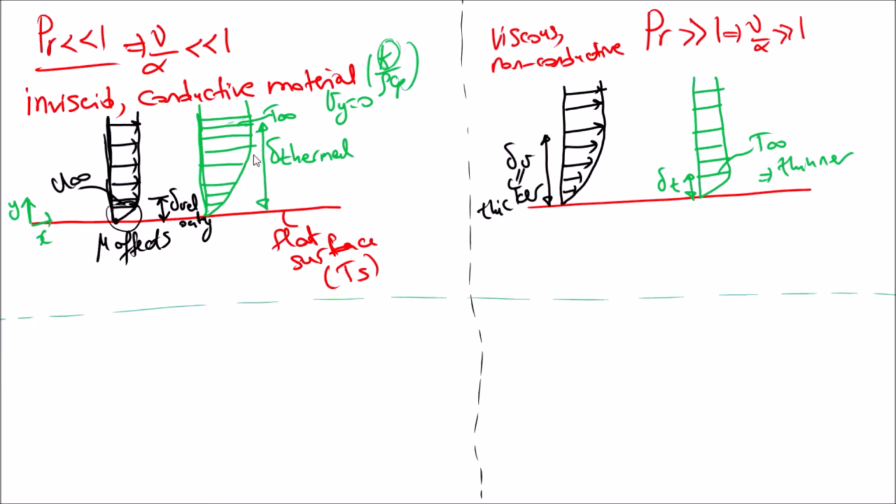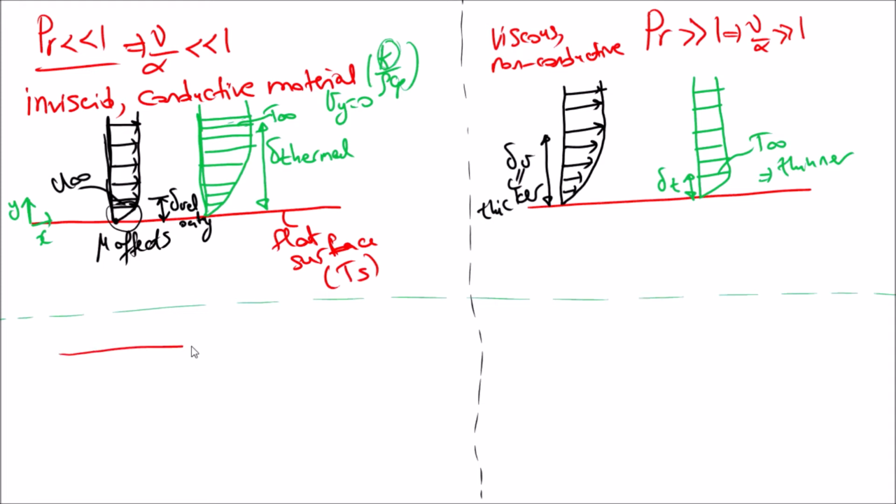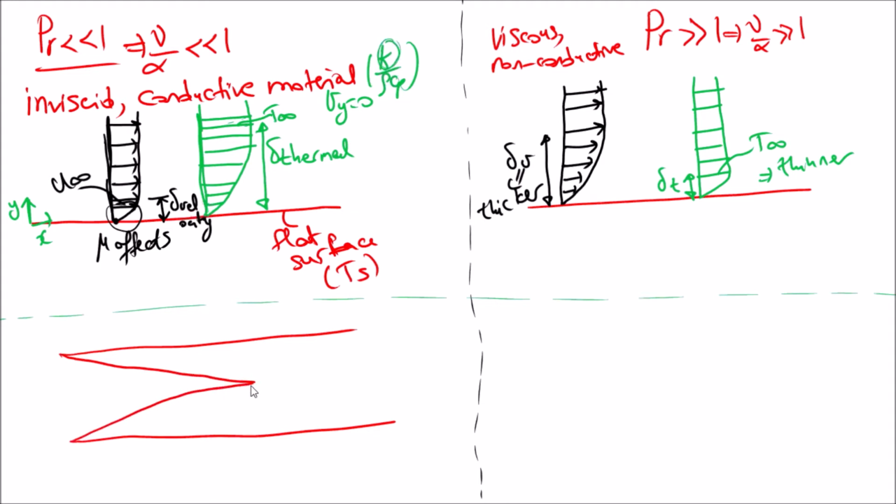Second importance of the Prandtl number is that if the Prandtl number is low, so if you go, this is your pipe. If Prandtl number is much less than 1, we have said viscosity is small. If the viscosity is small, then the boundary layer grows at a very low speed. Okay. If it grows at a very low speed, then this will be the velocity entry length.